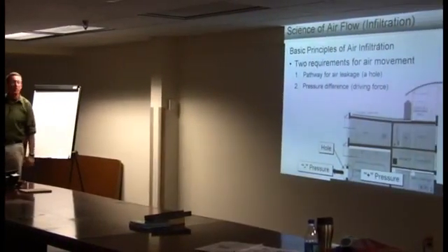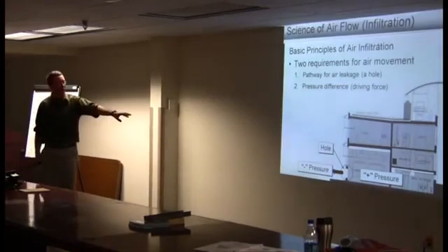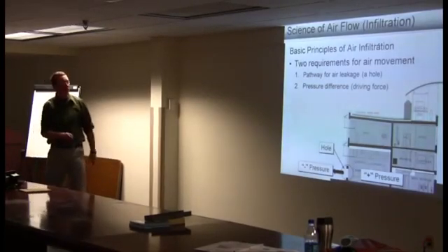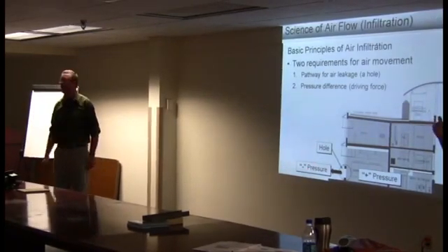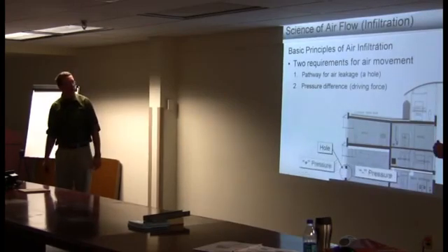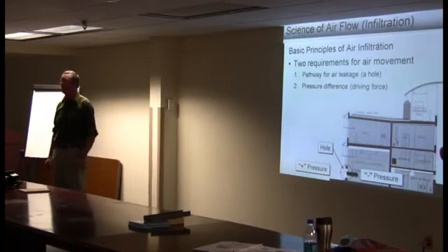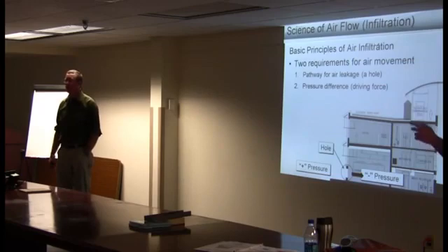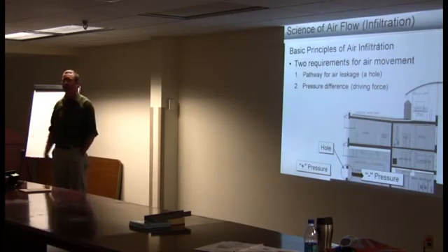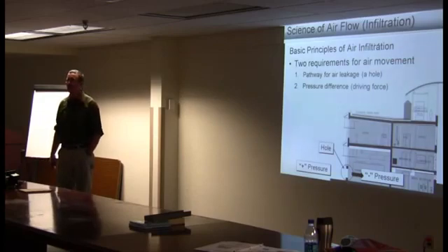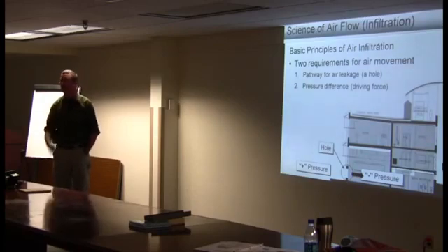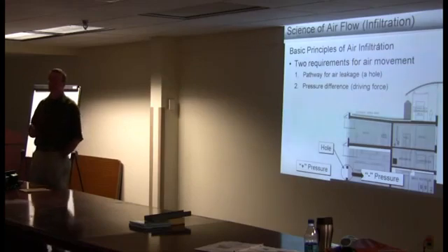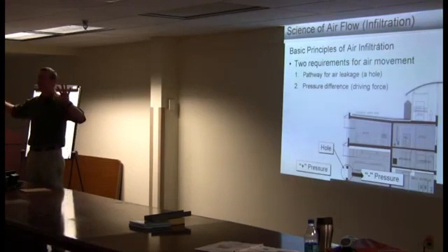In general, would we rather have our building look like this, where the building is positive with reference to the outside, or would we rather have our building look like this, where the building is negative with reference to the outside? What's our preference here in the South? Do our buildings want to be positive or negative? Why is that? Why would we rather have our buildings positively pressurized? Humidity. I think a lot has to do with moisture and basically keeping the humidity at bay, so to speak.